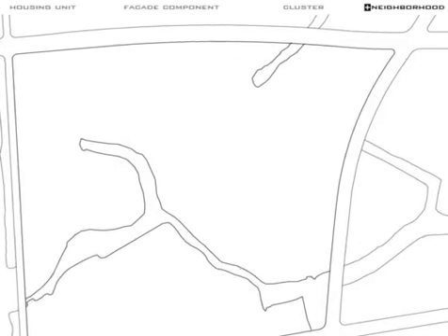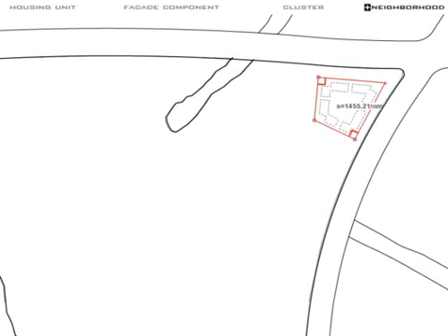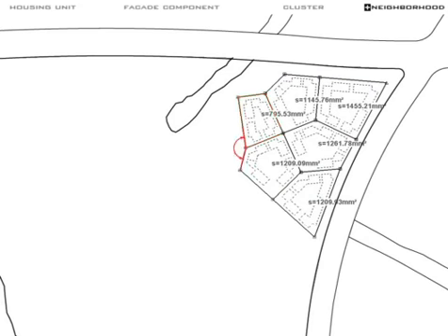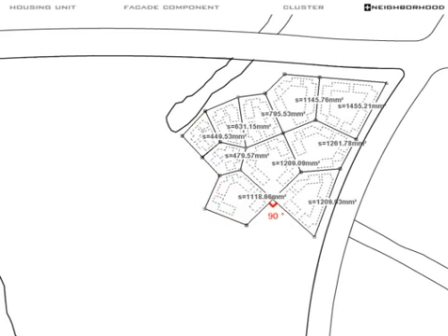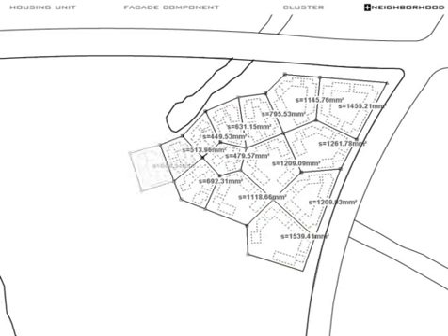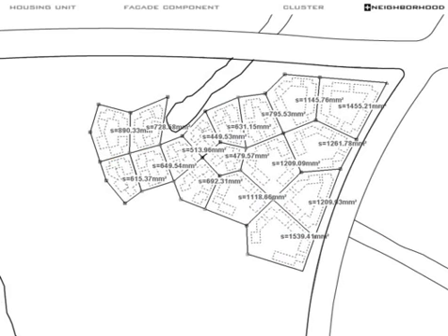By applying the housing plot on site, this geometrical model shows how new plots are generated out of the existing ones. 3 existing site conditions are considered: angles less than 90 degrees, between 90 to 150, and finally between 150 to 180 degrees. 2 things are considered: the size of the polygon, which relates to the FAR value, population density and income group, as well as the orientation for each side in order to make sure that each apartment receives sufficient sunlight. Different simple strategies in accordance with the land value map are applied in order to generate the proper size and orientation of polygons to fulfill the economic requirements.